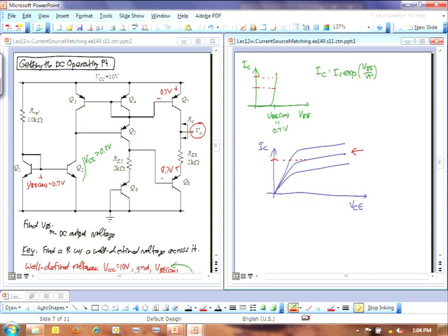You can see that I could get approximately that current over a quite high range of voltages. The slope here for that current is not going straight up. That's a pretty flat slope across there, which means many VCEs can support that current. So VCE is not a well-defined voltage for a given current, and this is well-defined.